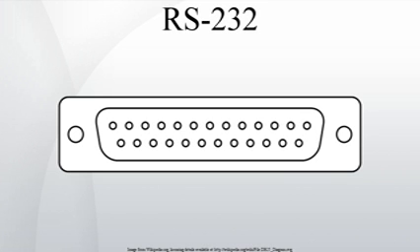Examples of control lines include request to send, RTS, clear to send, CTS, data terminal ready, DTR, and data set ready, DSR. The standard specifies a maximum open circuit voltage of 25 volts. Signal levels of ±5 V, ±10 V, ±12 V, and ±15 V are all commonly seen, depending on the voltages available to the line driver circuit. Some RS-232 driver chips have inbuilt circuitry to produce the required voltages from a 3 or 5 volt supply.